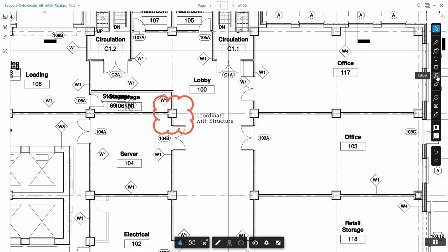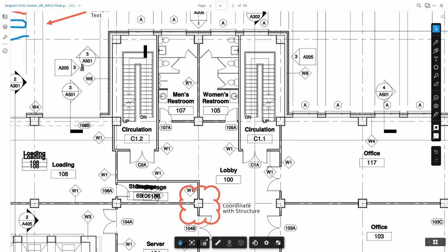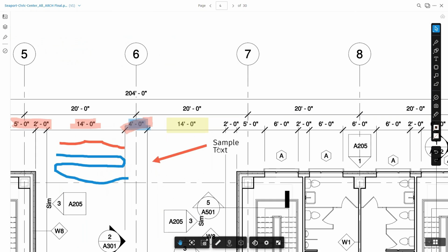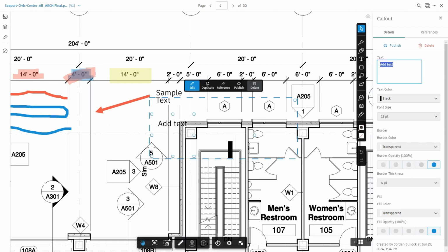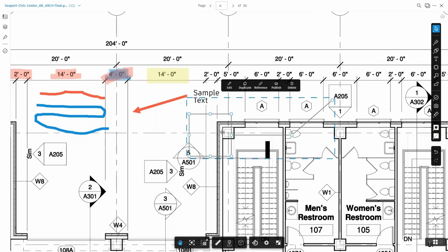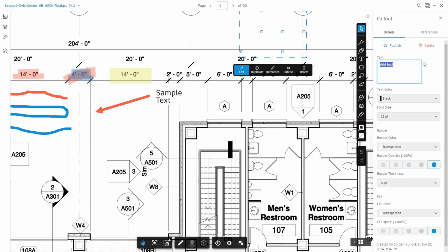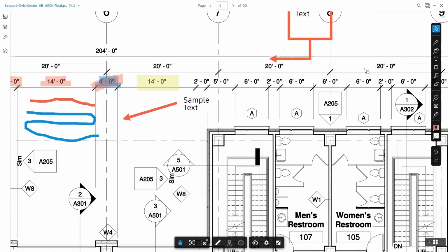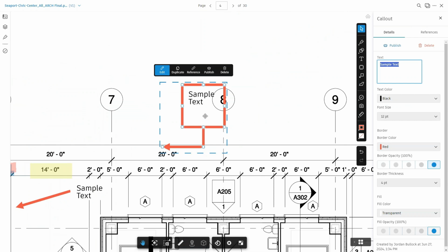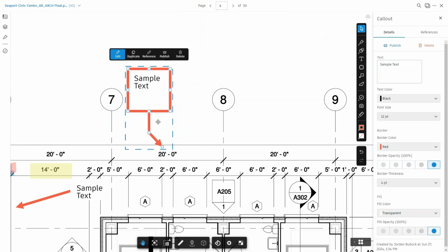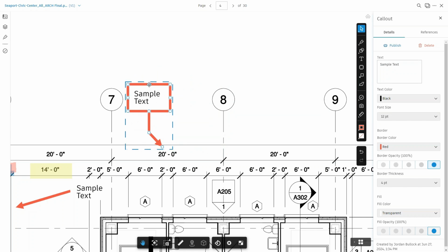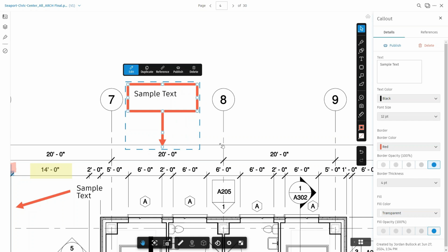And then as you're navigating through, you do have a call out box as well. So up here, I made a manual call out by using the arrow tool and basically a text box, but you do just have a quick call out tool as well. So as you're coming in here and as you're clicking on each of these devices, you do have the ability to essentially start drawing an arrow. Sorry, I have everything set to transparent right now. You can add your text in here. And then on your call out tool, you actually have all of these grips options. So as you move, you can see that the arrow stays in place based on the placement of that, but these are all intuitive. That way, each of these nodes basically gives you a different grip that you can draw, grab, and extend in the field.